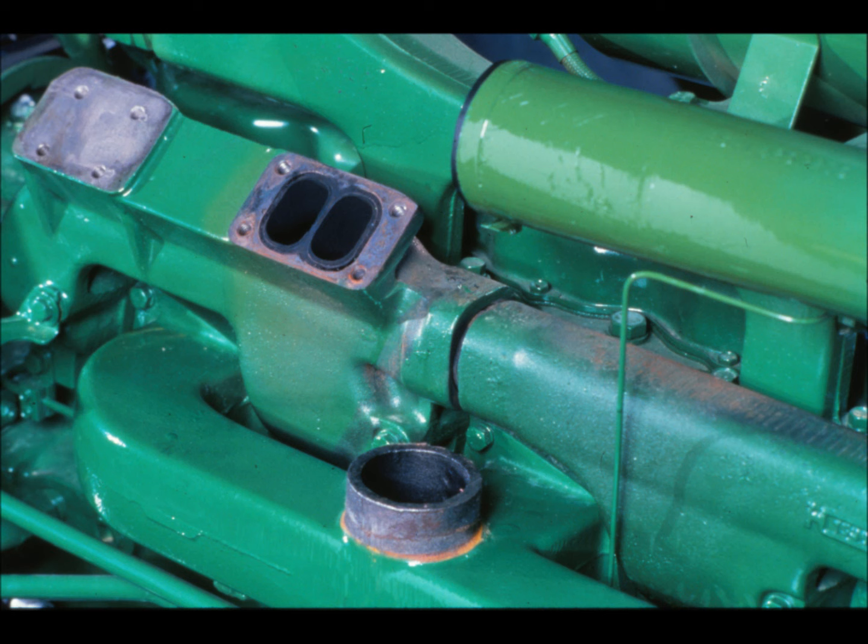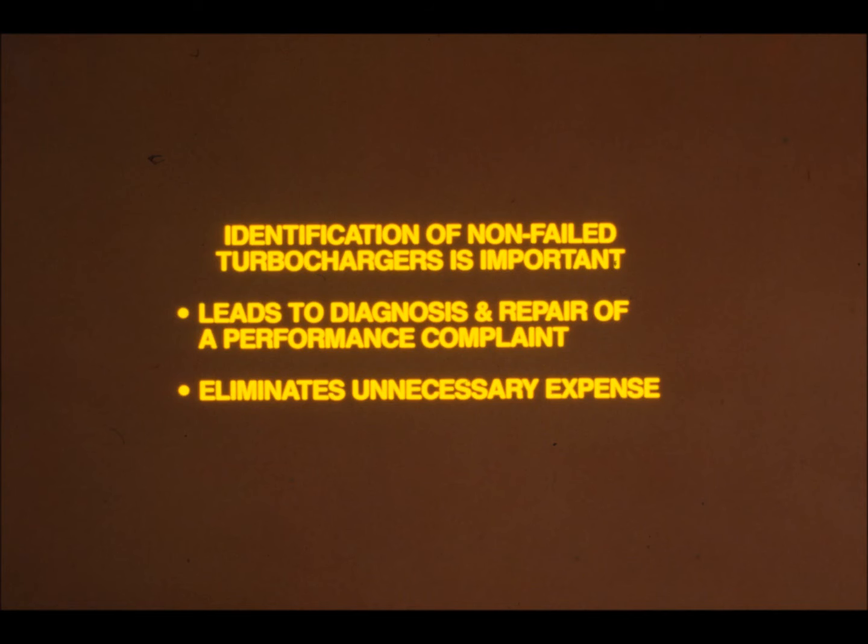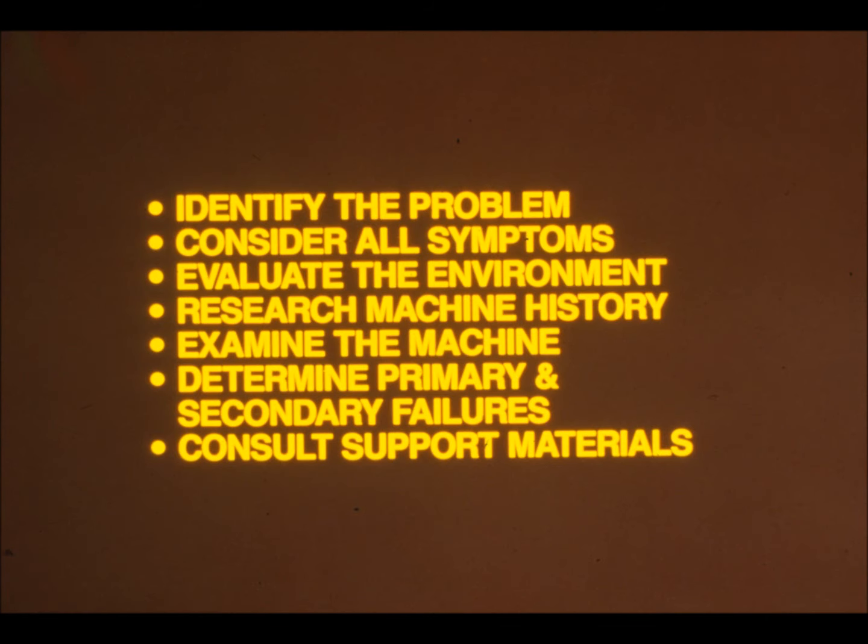Proper diagnosis of a non-failed turbocharger is important for two reasons. First, identification of a non-failed turbocharger will lead to further investigation and repair of the cause of a performance complaint. Second, proper diagnosis eliminates the unnecessary expense incurred when a non-failed turbocharger is replaced. The 7-step failure modes analysis procedure is recommended to assure that the cause of a failure is properly identified.